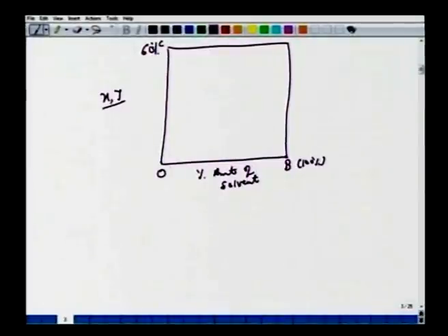So here we have X and Y, and if we plot, then this phase diagram will look like this, and somewhere here let's say this is 50. So again when we have the equilibrium diagram like 0, 10, say 20, 30, etc., and we are writing C here, that means this is a mole fraction of C in the X or Y phase.